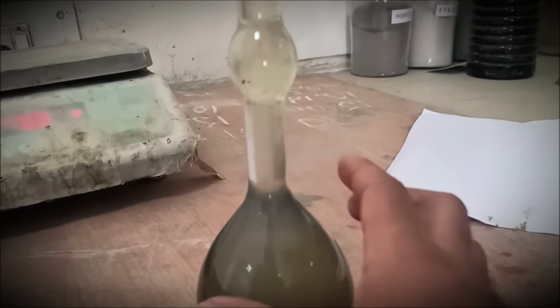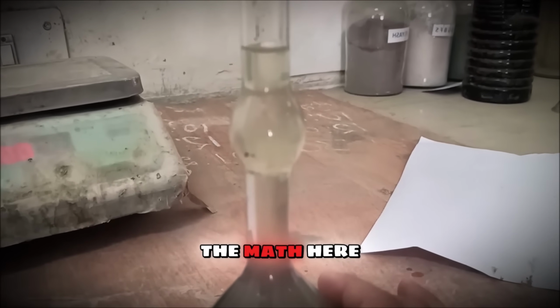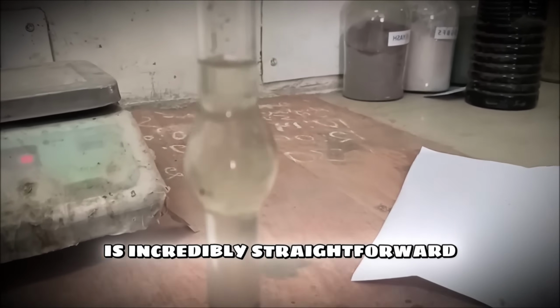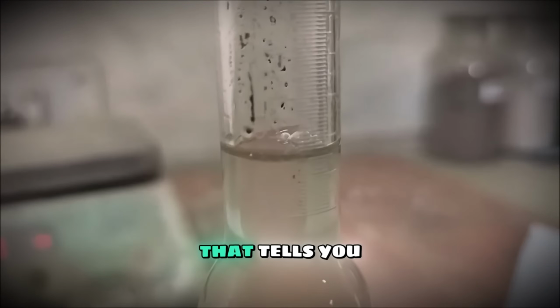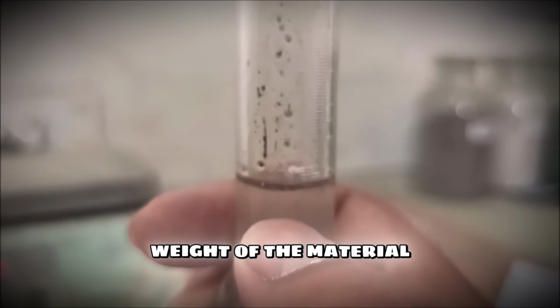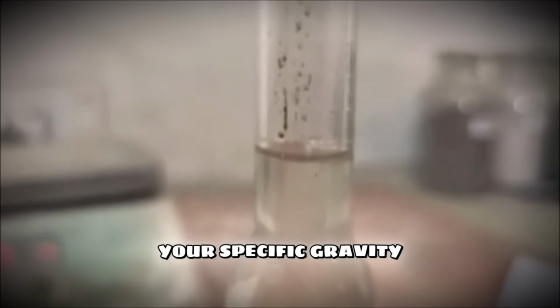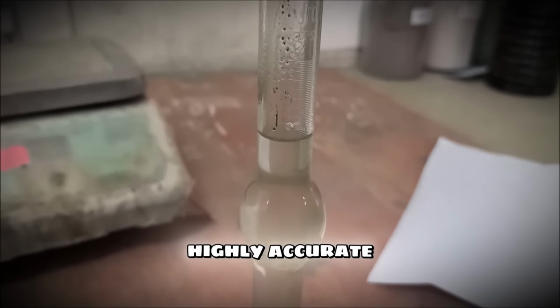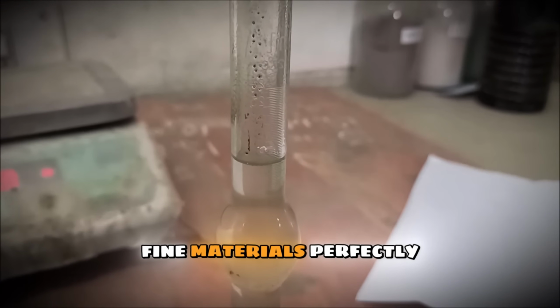Step 4. You read the new, higher liquid level on the graduations. The math here is incredibly straightforward. You subtract the first reading from the second reading. That tells you the exact volume of the material you poured in. You divide the weight of the material by that displaced volume, and you have your specific gravity. It is fast, highly accurate, and solves the problem of reactive fine materials perfectly.